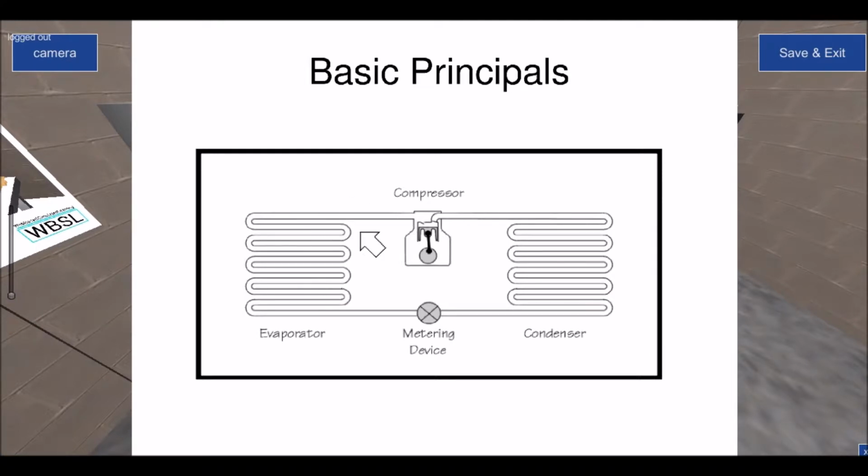And then again, back to the rate of compression, the compressor will pull the resultant vapor from the evaporator at the exact same time that the vapor is being produced, and at the exact same time that the condenser is calling for the refrigerant to enter into it. So balance point basically means that when we size these components, we must make sure that if anything goes wrong, we replace like with like, for example. Or if the condenser gets dirty, you're upsetting the balance point, and that's why you're not achieving temperature inside here. In other words, you're not absorbing the heat.